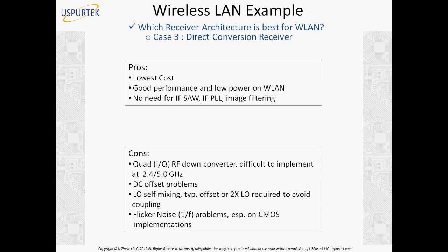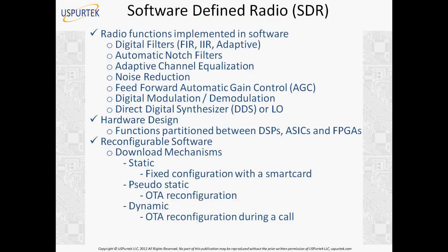If you are an electrical engineer, you always study about the phase lock loop, PLL, in your college course. So what happens here? The phase lock loop is basically used to maintain a stable frequency of the oscillator. So it's a feedback mechanism. Any oscillator will generate some frequency, but how do we ensure that the frequency remains stable at, let's say, 4 gigahertz or 2 gigahertz or whatever frequency we are generating inside the receiver? So the phase lock loop is a feedback loop from the output to the input of the oscillator.